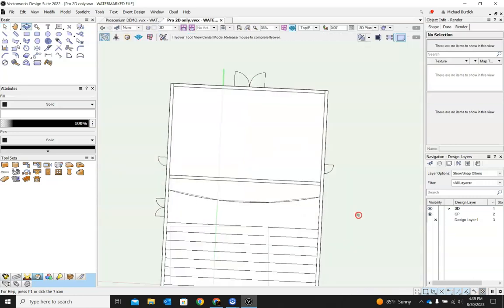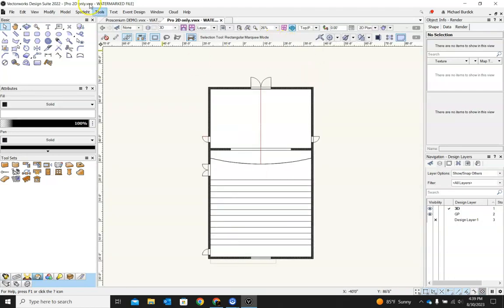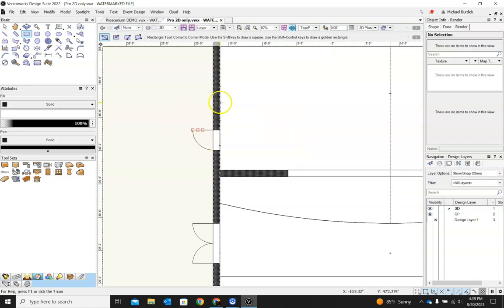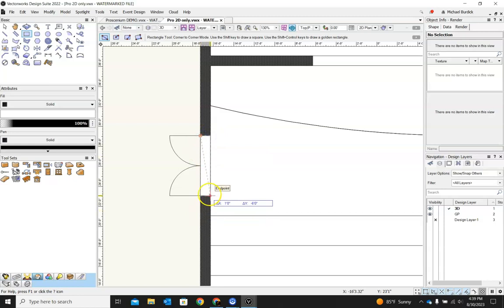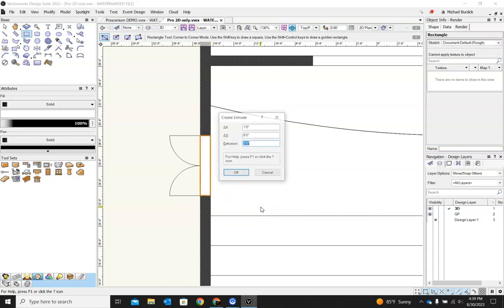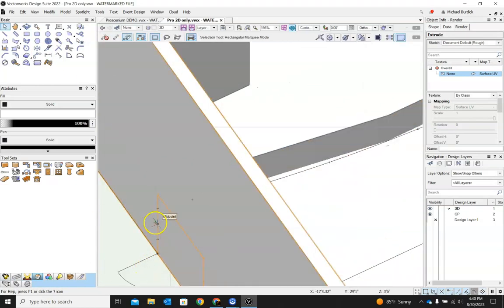So now let's go ahead and start dropping in real quick the rest of our doors on the top plan. So basically what we need to do is just draw shapes in space, and then we can subtract them from this solid. So this one is going to be the easiest. I'll just draw a little box there. I will extrude that up 7 foot. Again, all of these doors are really quite simple. They're the same 7 foot tall by 3 foot wide as in the black box. So now we have that object in the middle of the wall. So I'll select the wall also.